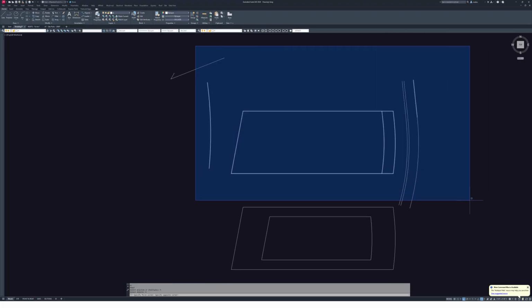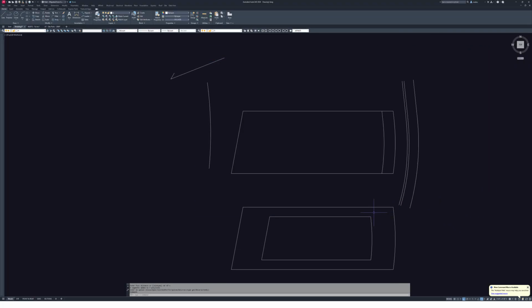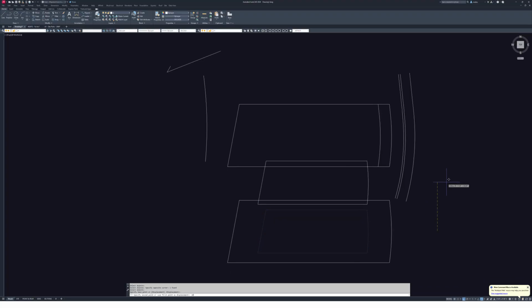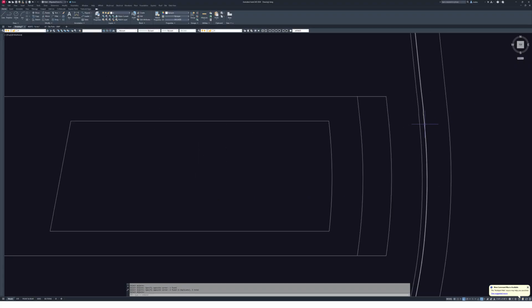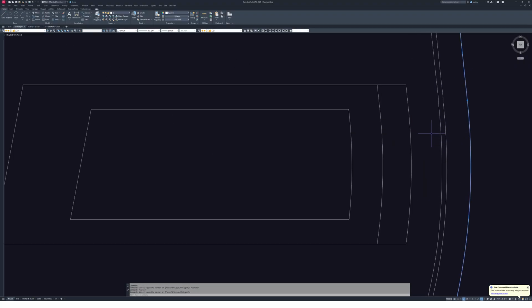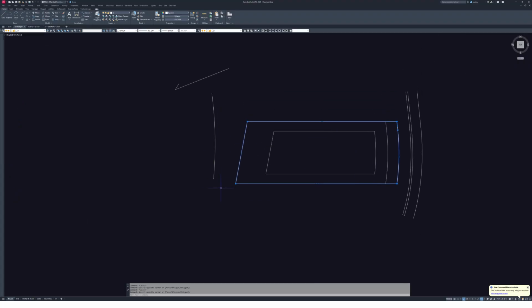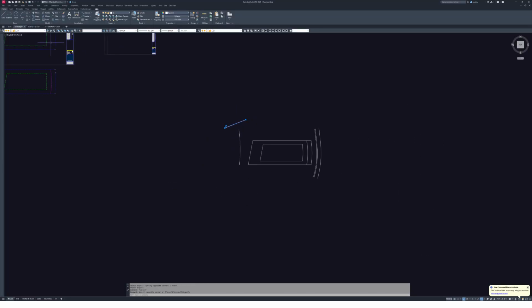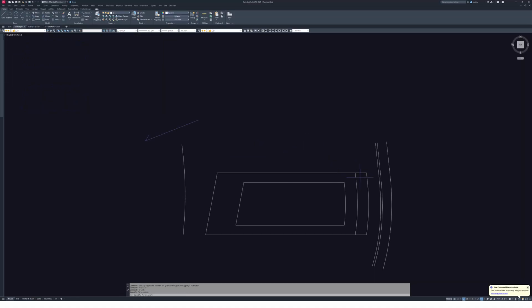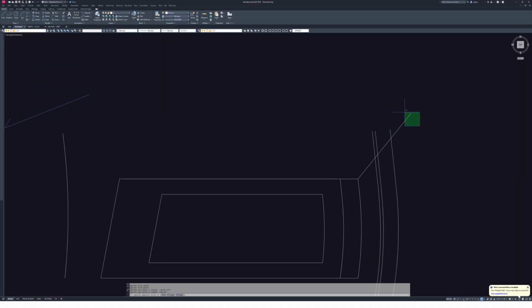And then I'm going to PJ all of this, which is just, again, remember my polyline join. I'll move this up 100 feet. Get rid of you. So now we have our curb, we have our center line of road, we have our easements and our water. Just project this down just to be clean. Throw this onto def points and make color 171. And just to be consistent, we will do this as well.